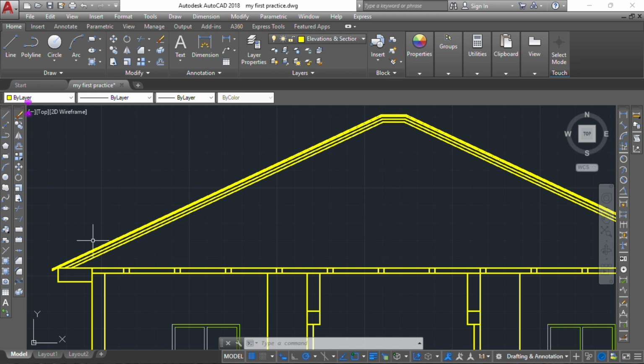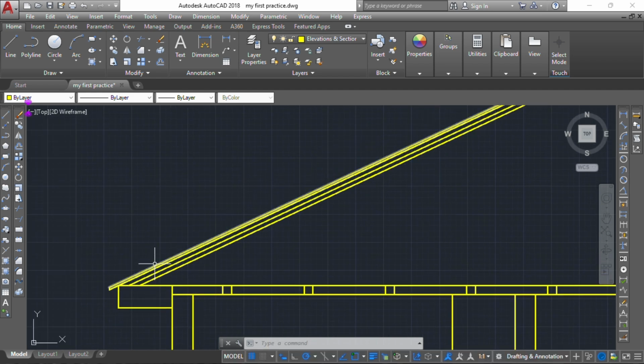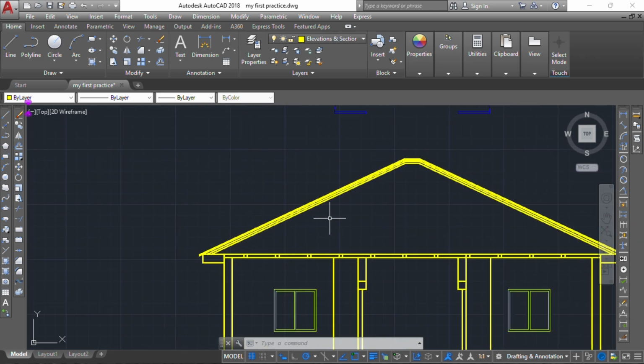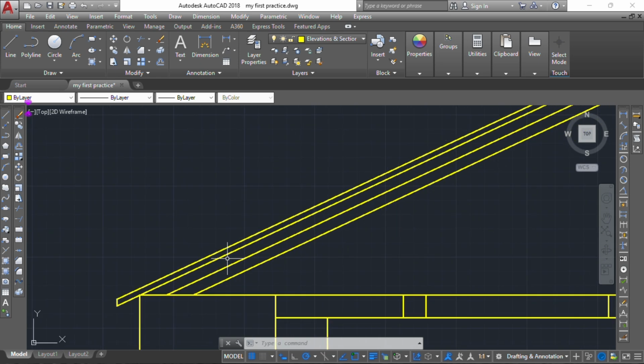Which will be in the middle here, and from there we'll be joining our rafter, which is the slant wood, which will be pinning down your wall plate here for your roof to the king post here, right? After that, we'll be having woods placed horizontally across our rafter to the other end of the roof. So now let's just go ahead and do that.